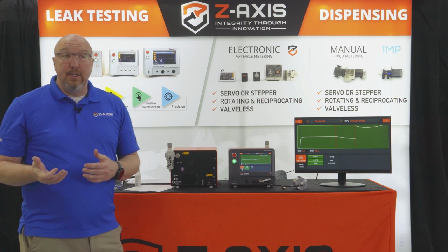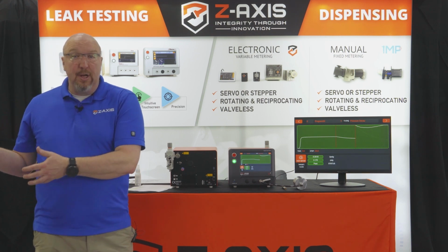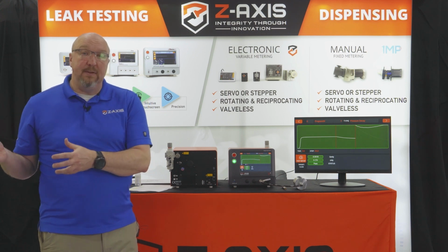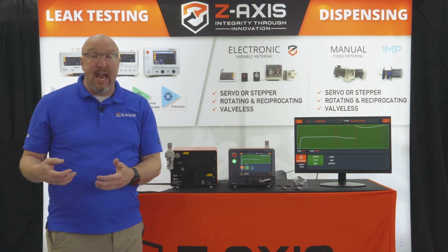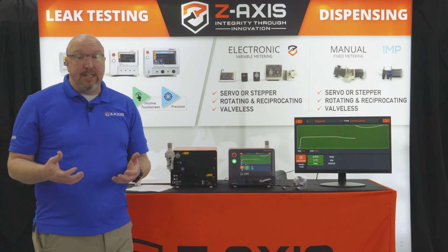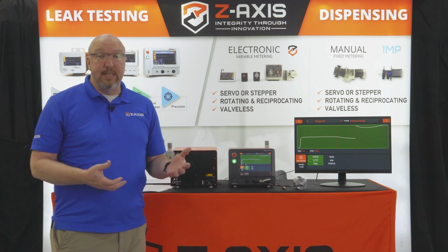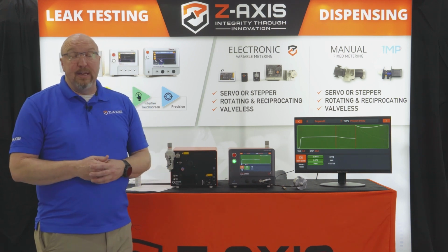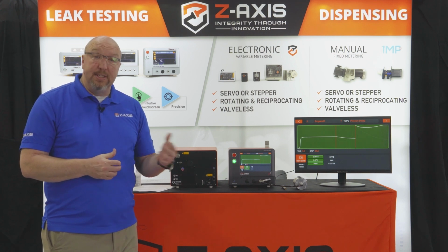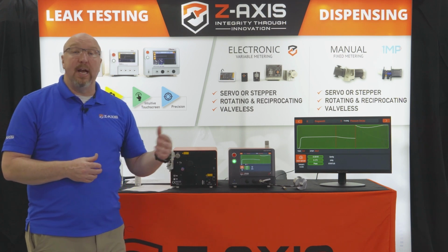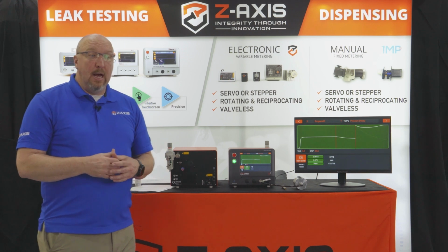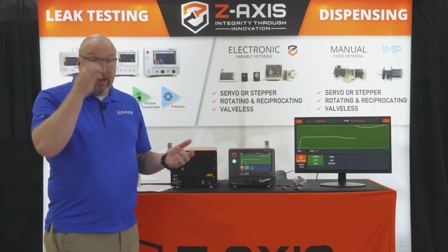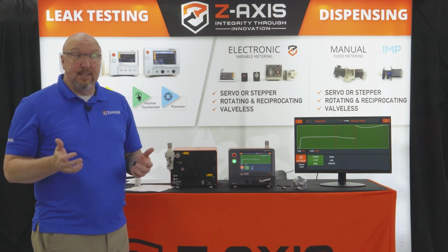A lot of times when the part is engineered and designed, it's been designed to do something specific, and so a specification could be handed down saying this part needs to be IP rated, for example. Ingress protection is where we're trying to make sure something is watertight to a certain depth, watertight to 1 meter, watertight to 10 meters. So knowing that spec, we can transfer that in and say, okay, where does it stand as far as an air leak?